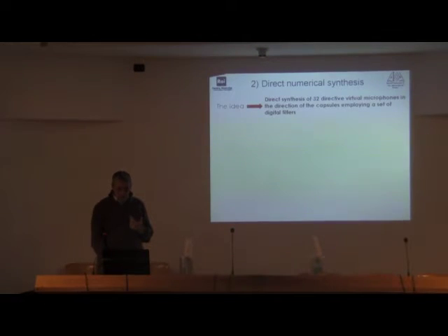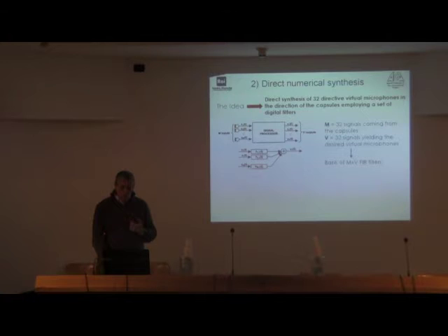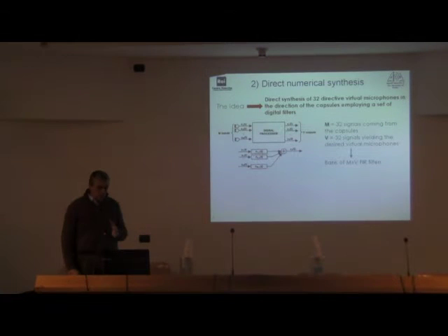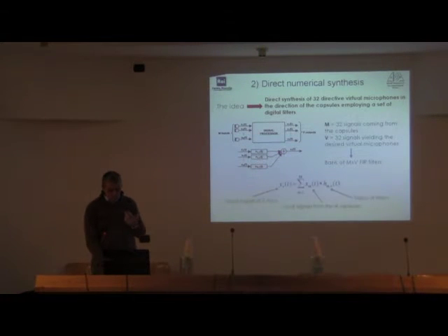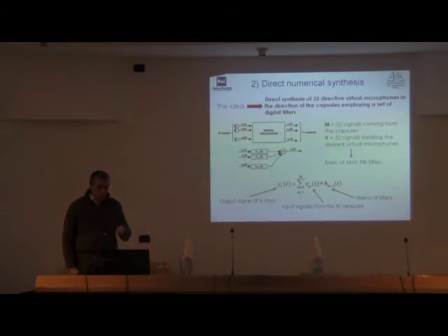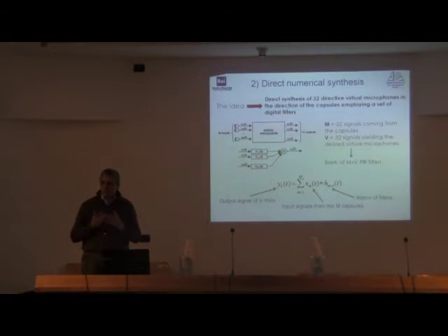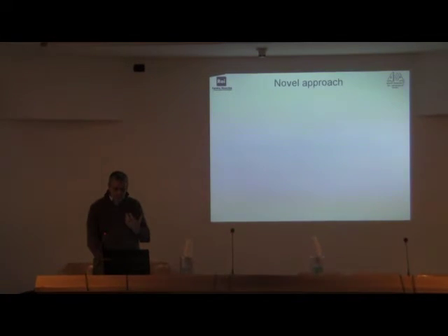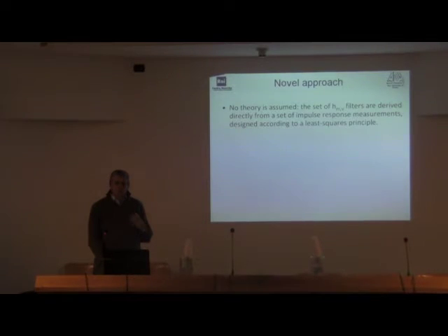The idea was to make a direct synthesis of the virtual microphone, again employing X-over, so employing a sum of convolutions. As you see, the equation is very simple. You get your signals from the microphones, you apply a number of FIR filters, and you sum the results. Very simple. The trick is how to design the filter coefficients. We don't use any theory. Our solution is completely numerical.